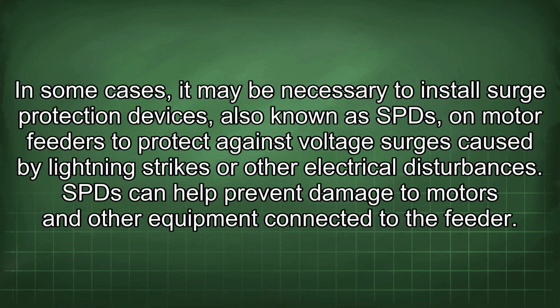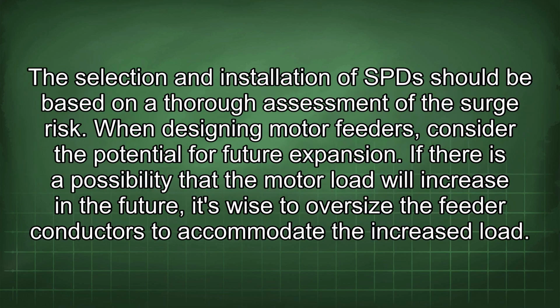In some cases, it may be necessary to install surge protection devices, also known as SPD, on motor feeders to protect against voltage surges caused by lightning strikes or other electrical disturbances. SPD can help prevent damage to motors and other equipment connected to the feeder. The selection and installation of SPD should be based on a thorough assessment of the surge risk.